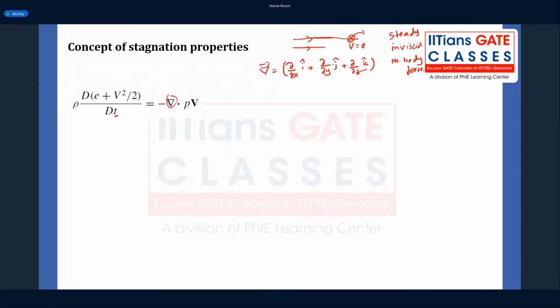I'm not going to ask whether it's a conservative form or non-conservative form. You might not have been introduced to different forms of governing equations, but let us leave it at that point. Maybe in your actual classes, you will be introduced to all those terminologies and classification. Looking at this particular form of energy equation, can you guys tell me what assumptions are already involved? This is not a full energy equation. This is a reduced form of energy equation. Just looking at this equation, can you straight away tell me what assumptions are involved in this particular form?